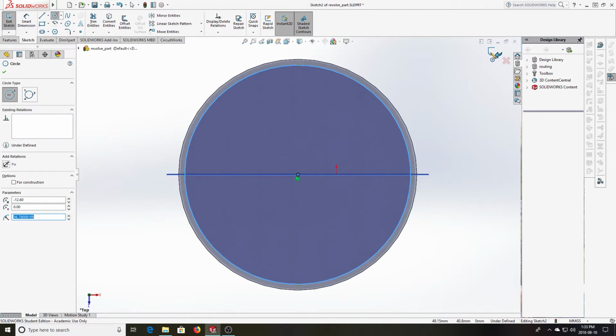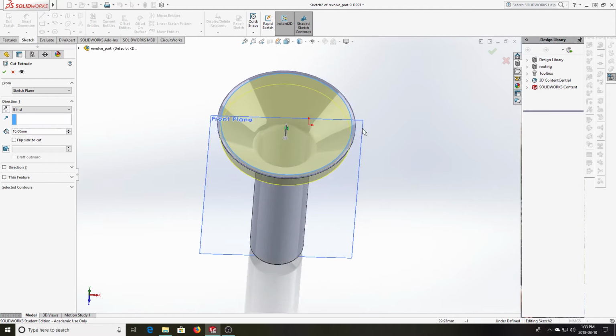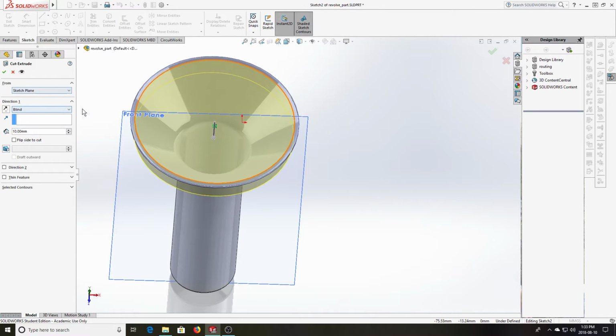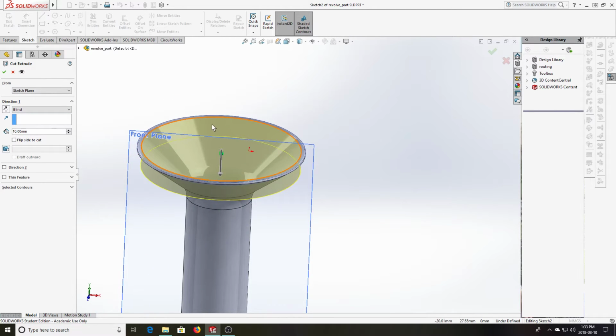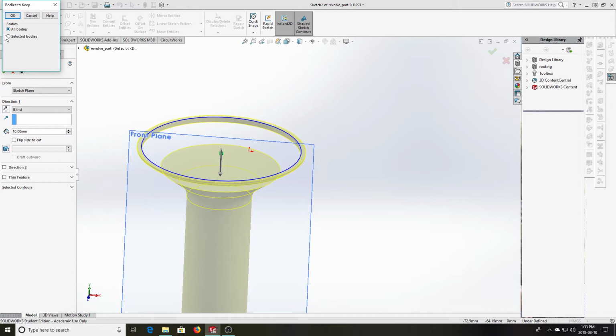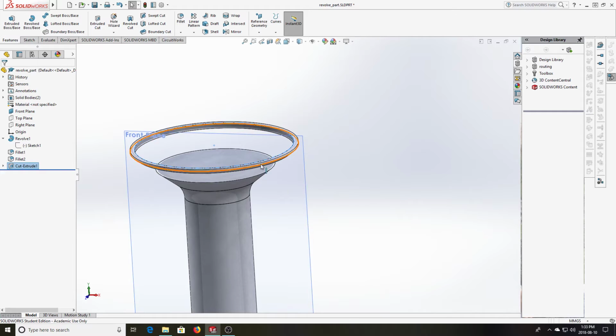And if I leave it at that, and I say there, I've just drawn my circle, and I select it, then the cut that SolidWorks now thinks I want to make is inside the circle. And as you can see, if I accept that, it will happily do it, and it'll complain that I've just made several bodies. And it's done this goofy thing where it actually cut the outer ring out, because it cut the inner closed region of the circle that I made. So that wasn't what I wanted.